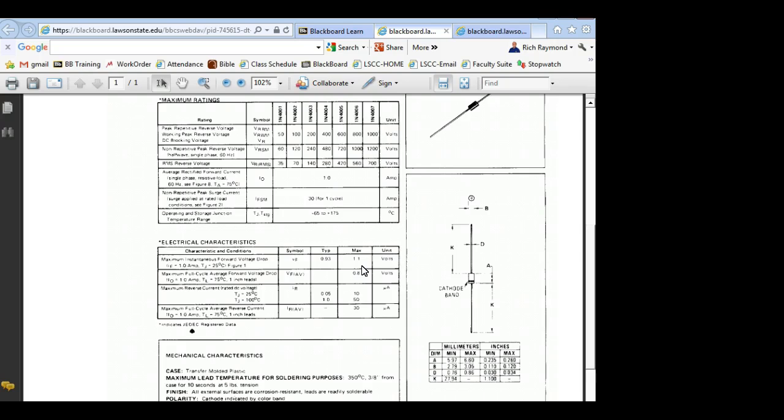Y'all understand that? If I wanted to know the actual voltage drop, then that's going to take a lot of math that we don't need to use, because the 7/10 of a volt is okay, right? Especially in a technology where our math is perfect, but our components are not. So there's very seldom in electronics that you're going to calculate exactly what you're going to measure.